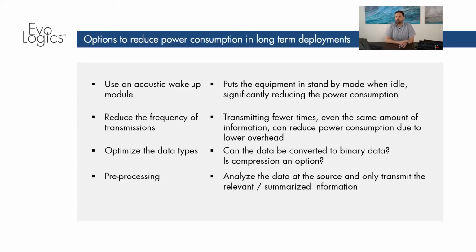So how can you reduce the power consumption? This is a very important thing for long-term deployments. The first option is to use an acoustic wake-up module. This will put the equipment in standby mode, so when there's no transmissions, the power consumption is decreased considerably.